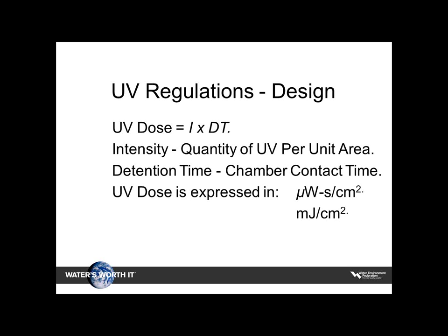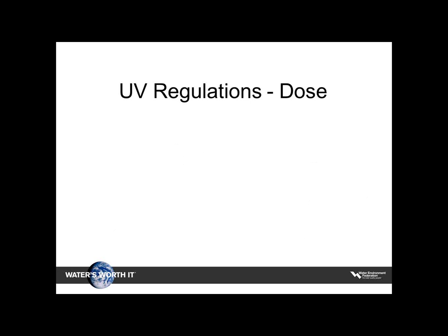And what's interesting on this, so again, with the regulatory all over the place, you may need to explain. Some regulations may say it's in millijoules, and you have to make sure everybody knows the conversion on this. 1 millijoule equals 1,000 microwatt-seconds, because that's one of the things you have to deal with. Now, just looking at some of the regulatory requirements of dose, I'm just looking at some of the Wild West states around here. Colorado actually requires greater than 30 millijoules per centimeter squared.